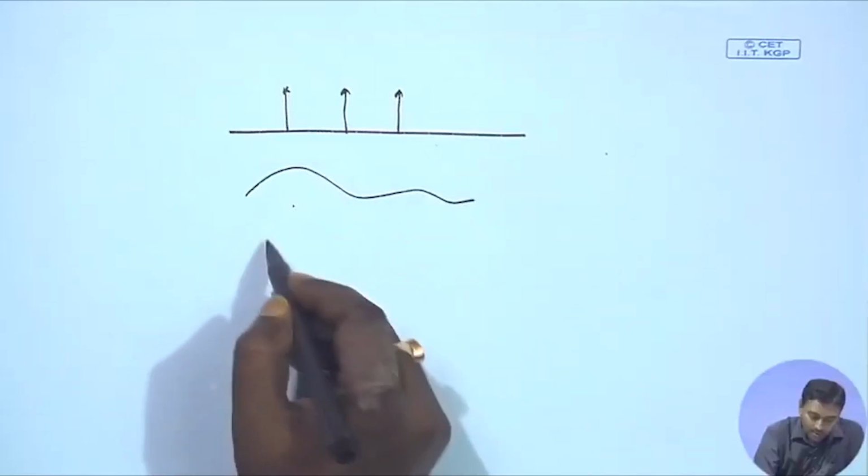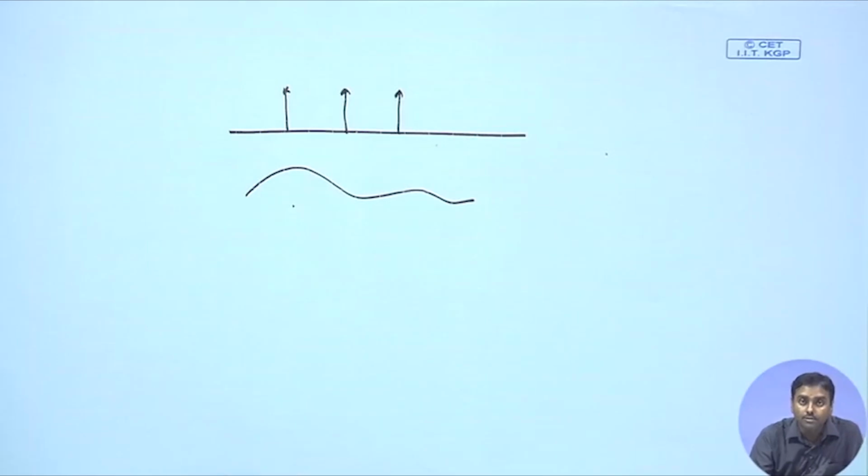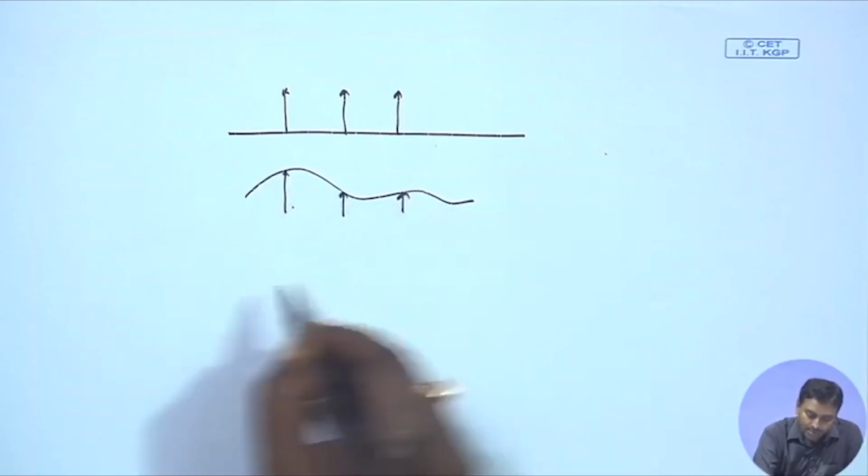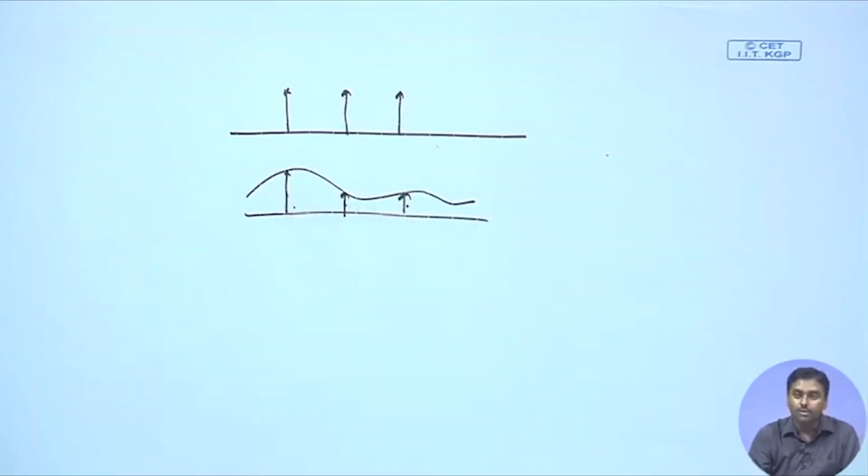With that we started doing almost like pulse amplitude modulation. Because it is an impulse function, we were treating it as if we were taking samples of the signal. If we had a signal and multiplied it by delta, it would just pick the sample at that instant. These sample values were represented as discrete time, continuous amplitude. So, it is still an analog signal.